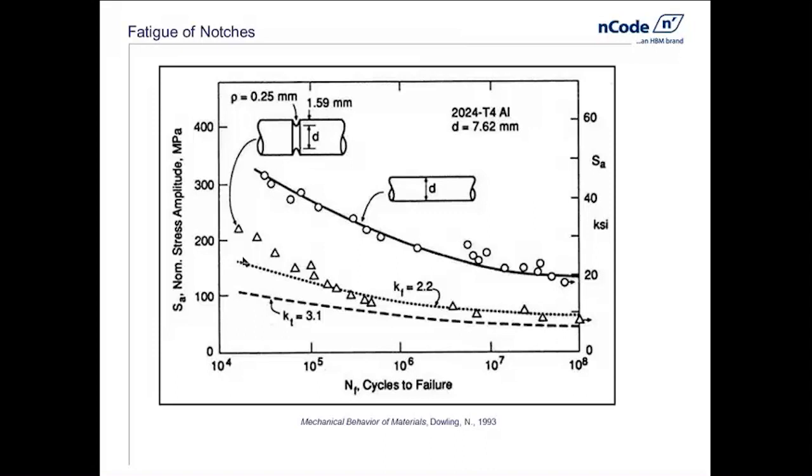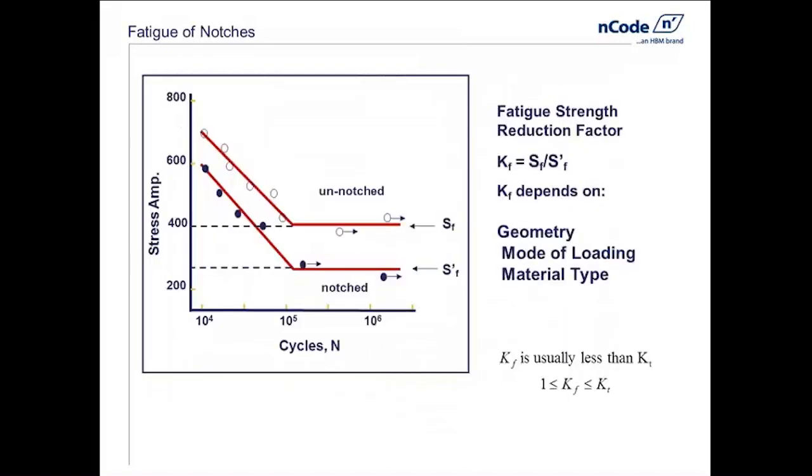The key here is the material that this part was made of is not completely notch sensitive, and so that stress at the notch isn't fully effective in fatigue. Another way to look at this is if I have, again, a fatigue curve of pure material, an unnotched specimen, and I then go in, take my notched specimen and test it, I will see I have a degraded performance. I have a fatigue curve that's lower. But that reduction isn't necessarily always the same as the stress concentration factor I get on my final program.